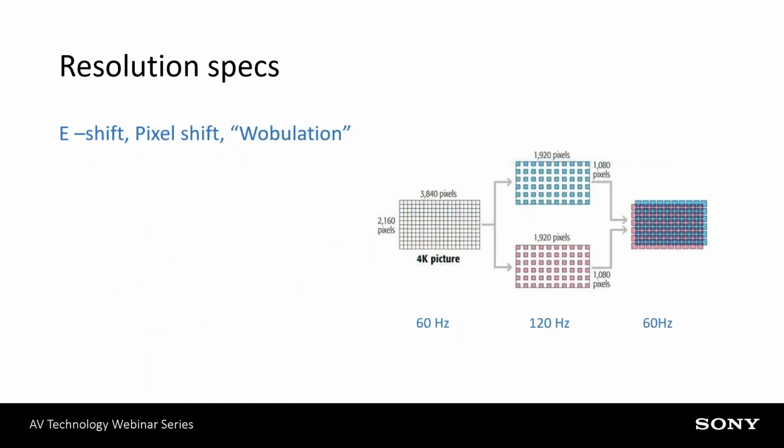This slide graphically shows how this works. I take a UHD signal and I break it into two HD signals and write it twice as fast. So the image of each HD signal is on the screen for 1/120th of a second, and then I show the other half. So every 60th of a second, I'm seeing essentially two frames of slightly shifted image. It actually works pretty well.